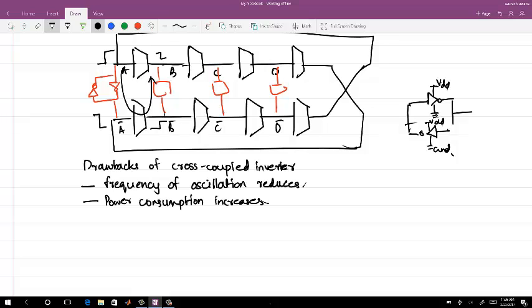Right now we are still seeing this as a gm cell, a transistor working in saturation. But soon we will see these are all inverters to get a higher swing, and true differential stages can only give you a limited swing. We will see that you can do that part. Odd number of stages will not give you the even phases which you normally require for IQ and their derivatives.